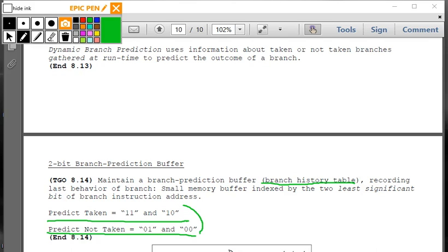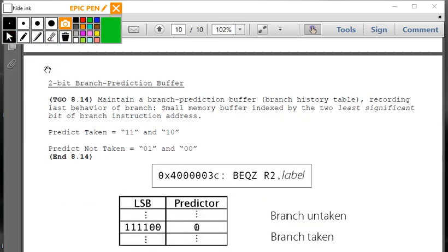And we get to the finite state. So the common question is, well, if we have 1-bit branch prediction, why aren't we just using 1 and 0 to differentiate? Well, you'll see how using this concept of hysteresis and making a more robust finite state machine will allow a more accurate prediction model. Because before that, what happens is if you have a 1-bit branch prediction approach, you're just